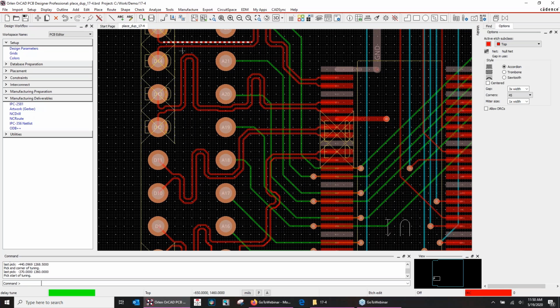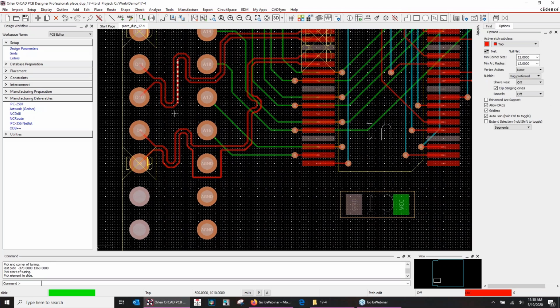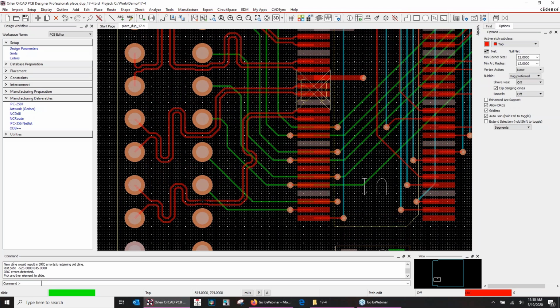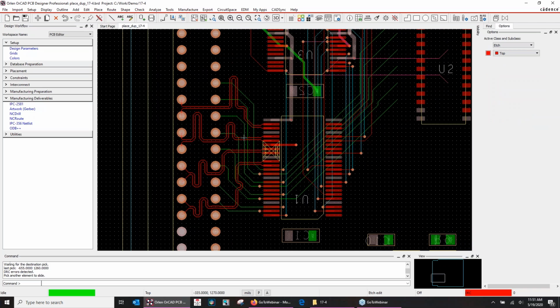But you're still seeing the DRC errors, right? Well, the problem is this got moved and wrapped around there, so I need to just slide that back. Notice the DRCs go away, except for this one, where I need some more tuning. But all those DRCs went away because now they're in phase and their delays are matching. I might want to clean this up because I had it centered between the two pads, and I can slide that with no real issues, just lining those up. And notice my 5 mil grid now helps me here. Instead of that 25 mil grid, I have the 2 grids, but it helps me in my tuning. So that's manual routing. That's routing some differential pairs.